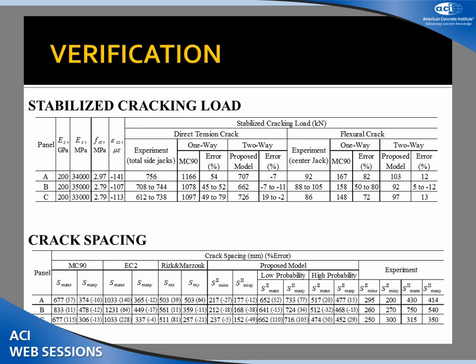Also, the crack spacing is compared with Model Code 90, Eurocode 2, and some equation from RILEM from another researcher. And we found better results from the proposed model than any of these equations.